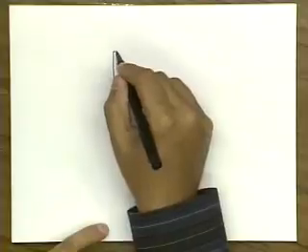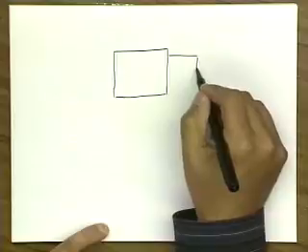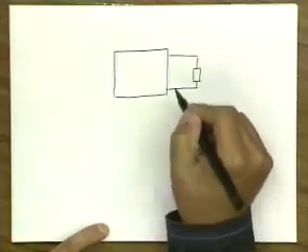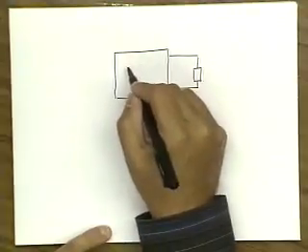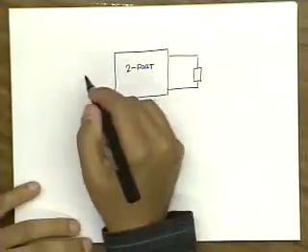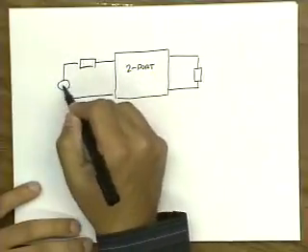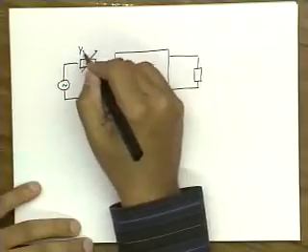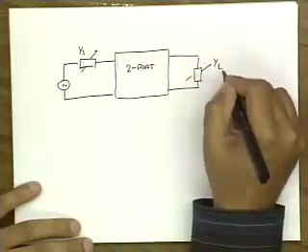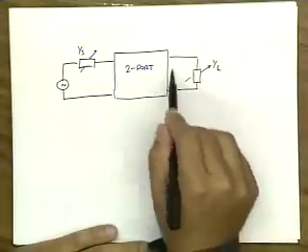All right, so let's recap where we were, and let's try to define the problem again as we did last lecture. The problem that we posed last lecture was we have a generic 2-port that could represent a single amplifier or a chain of transistors, a multi-stage amplifier. And we asked the simple question, what are the optimal source and load admittances such that we can transfer the maximum power to the load?